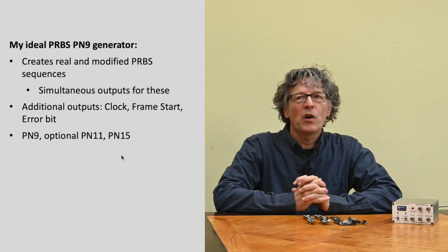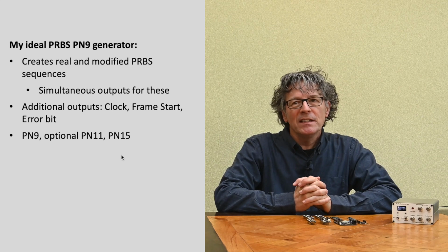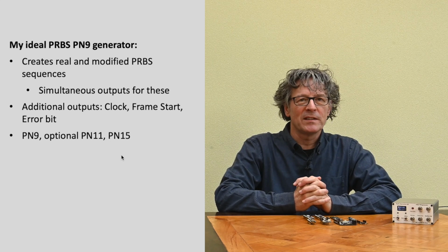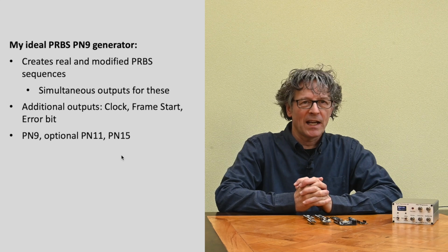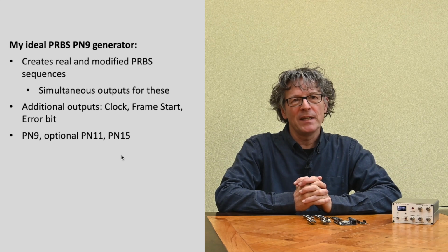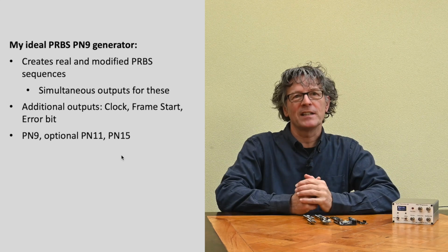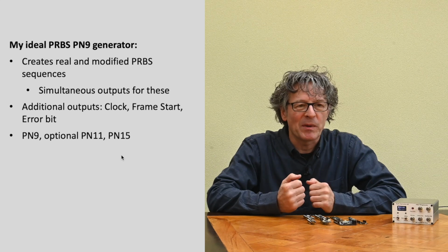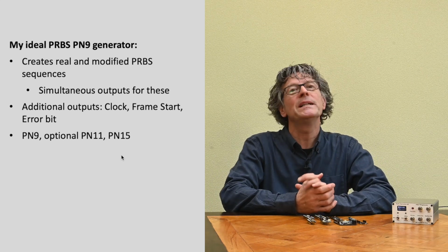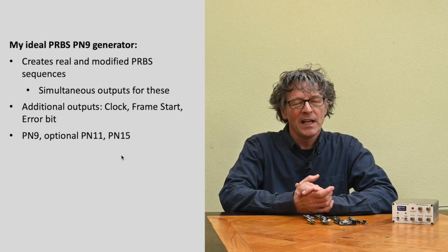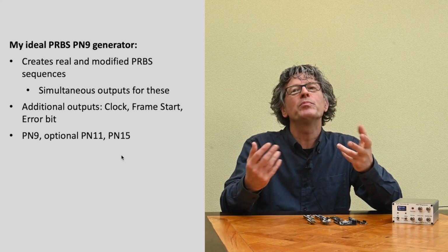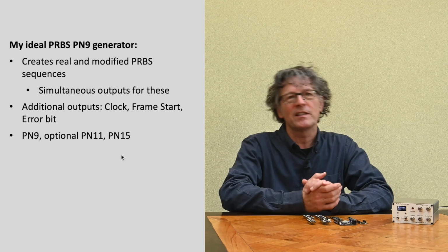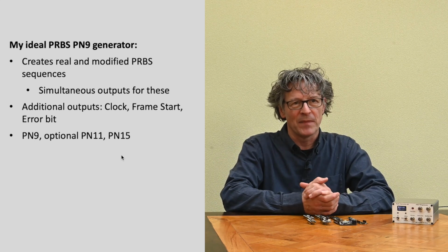Now, in my earlier video I already said a little bit about what my ideal PN9 signal generator would look like. It would create a proper PN9 sequence as well as modified sequences where I can introduce pre-programmed errors in certain ways. And ideally it would also output these proper and modified signals at the same time.